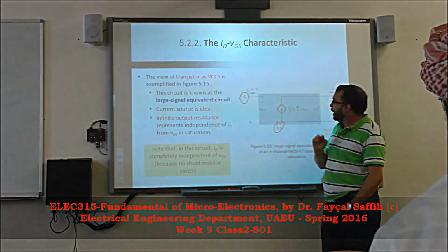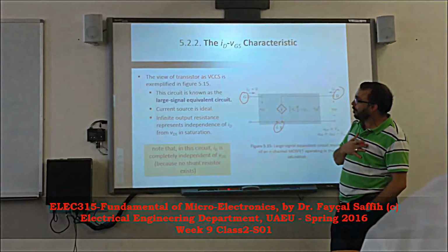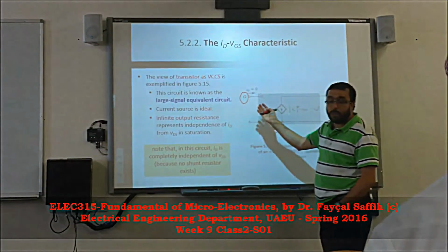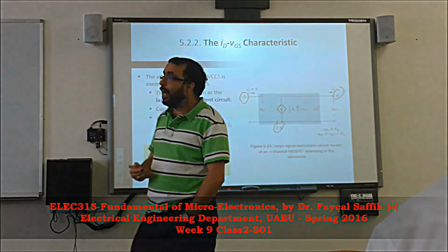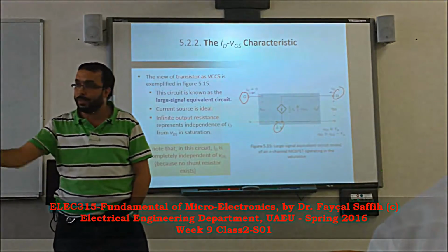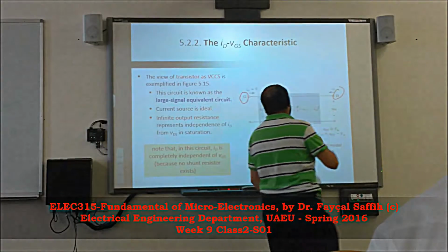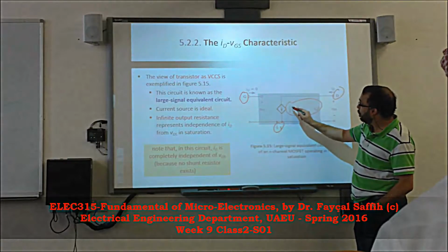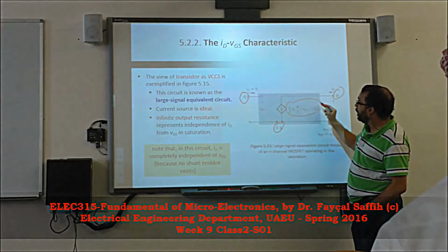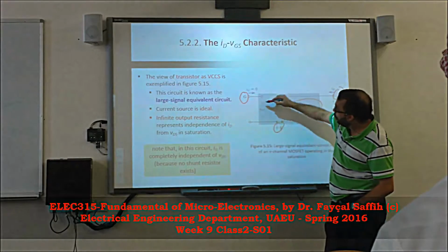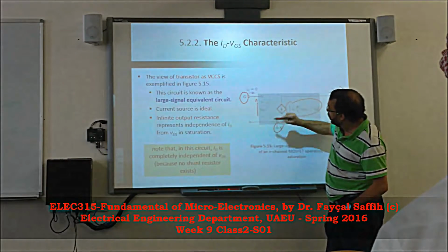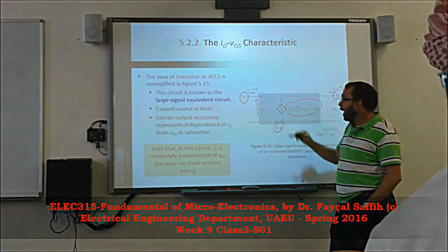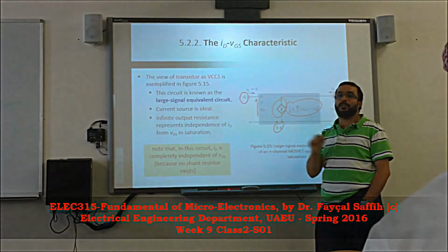Okay. So what do we say? I use, of course, my device, the MOSFET, as an amplifier. I have to be technically in saturation. This is my first condition. So for that matter, I know how much current the drain is supplying the source: it is equal to half Kn V overdrive squared, or (VGS minus VT) squared, which is this voltage. So I supply this voltage, I get this current. I increase this voltage, the current increases here, and this symbol is the symbol of the current source.